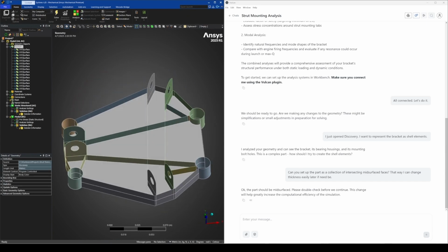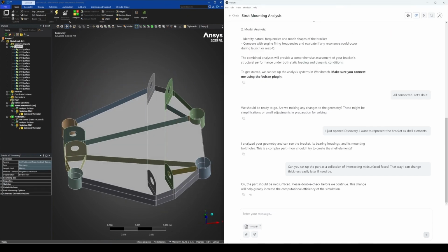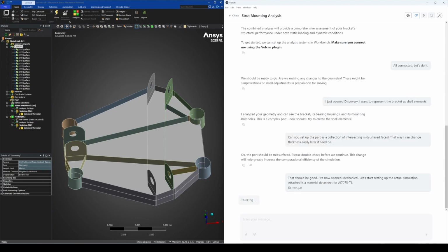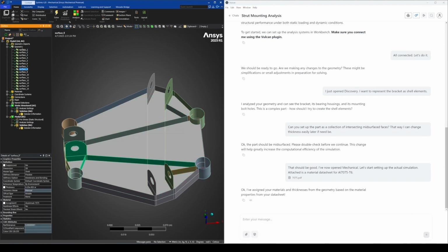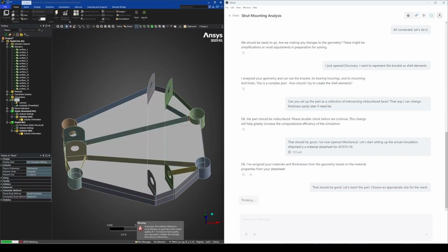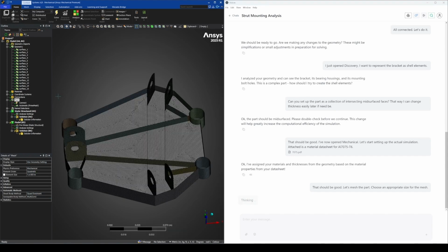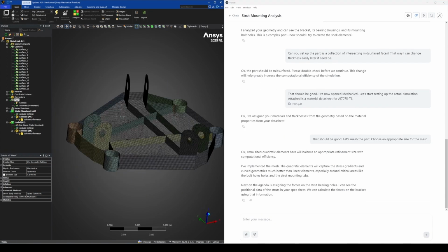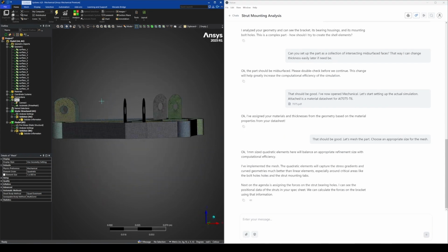We can now set material properties and thickness of the actual surfaces contained within the geometry via an upload of a PDF of 7075 T6 from MatWeb's online resources. For this situation, we can leave meshing up to Vulcan, which chooses a 1 mm quad size with mid nodes enabled and stitches all of the surfaces together such that they're all connected like the original geometric body.